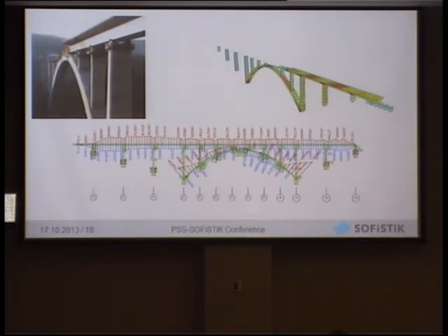So an experienced bridge engineer will immediately want to see this shark fin-like moment of the start segment of the bridge. And we will also check probably the moment of the arch here, because when the bridge is launched from here to there, the first approach here is quite critical, because we approach an asymmetric, antisymmetric loading for the arch and generate the following moment envelope after superpositioning of these construction stage results.